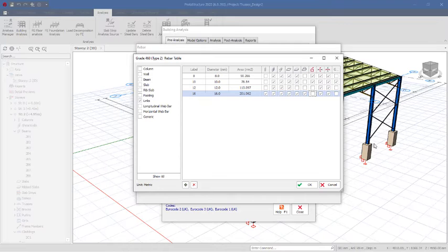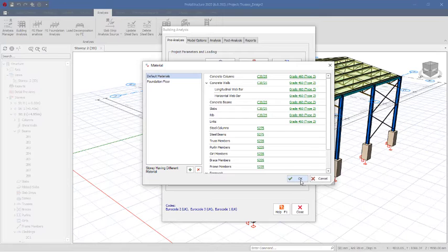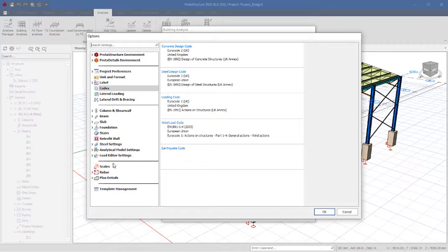Click on the OK option. But how about the foundations? Alright, for these foundations, you just have to uncheck this. Click on the footings right there. So come over to where you have our footings. Okay, we need 16 right there. We wouldn't need 20. We need 16 and 12. So you have to uncheck this to see other provisions. So over here we have 12. Yeah, this is 12. Okay, so we need 12 and 16 for the footings. Alright, so click on the OK option and then OK again. OK again. So we are done with the material settings. Alright, so you can go to setting center and be able to confirm all other settings in these provisions if need be.